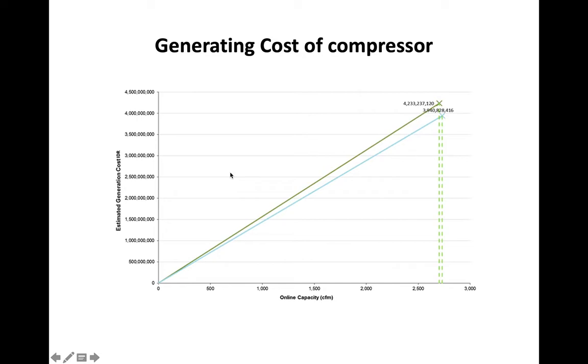In this case there are mainly two compressor rooms. Each compressor room consists of three compressors, but only two compressors operate in each room, so totally there are four compressors operating. But in actual operation, they will not operate all of the compressors. The compressors operate depending on the demand of compressed air from the end user.